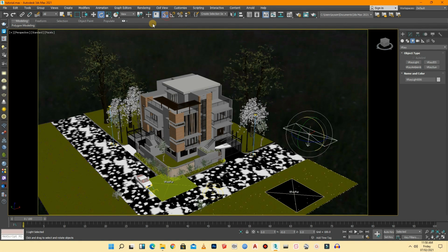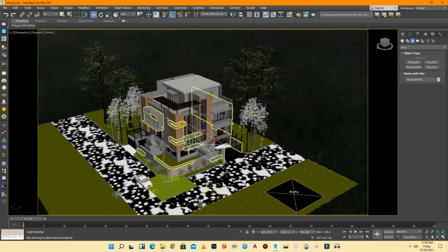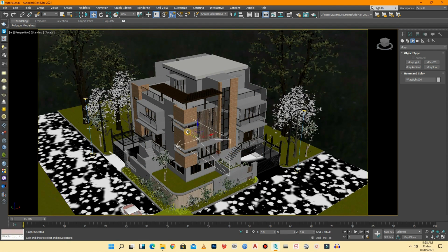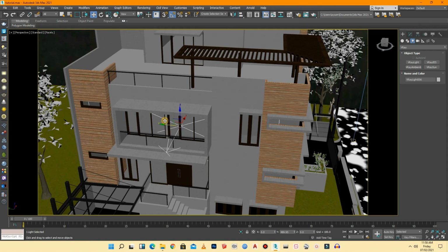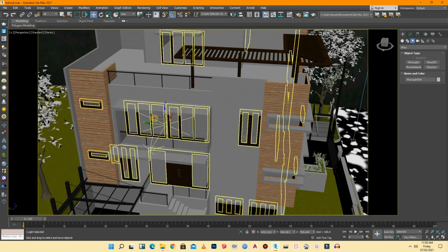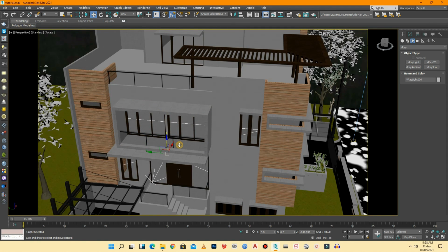and rotate, and make sure the angle snap tool is on so that you can rotate it 90 degrees exactly. So I will place these rectangular lights inside the building, inside the interior of the building. It's way too big for a floor.